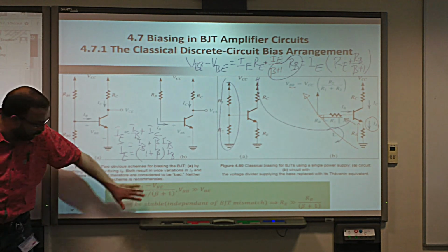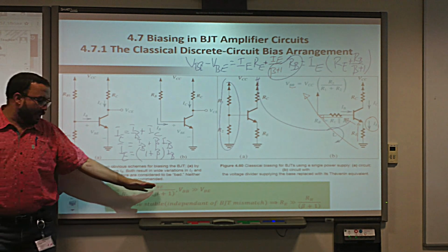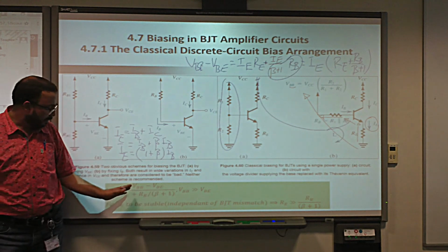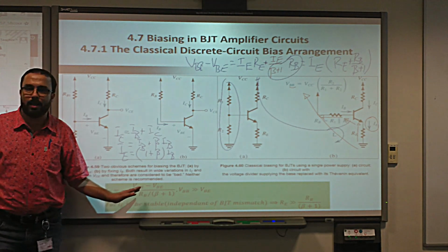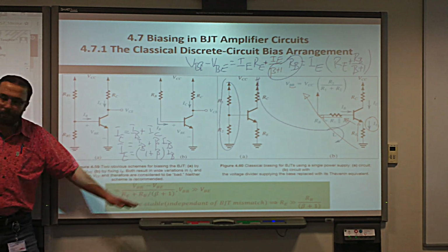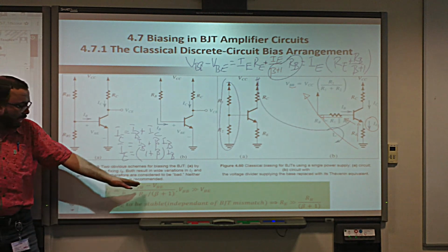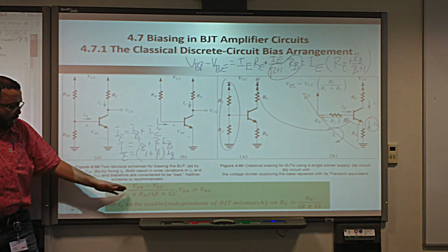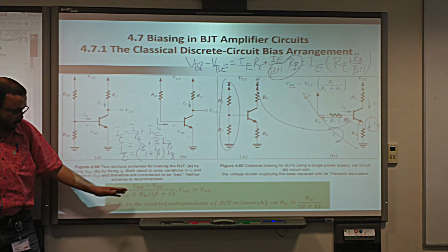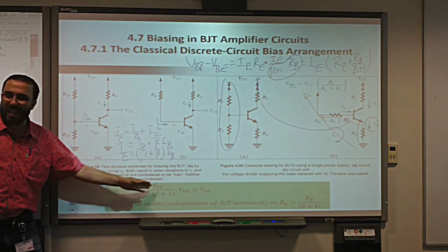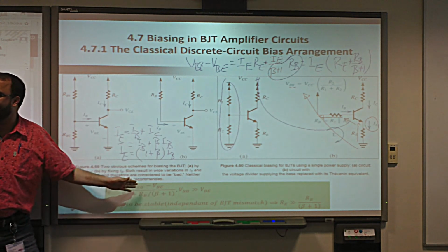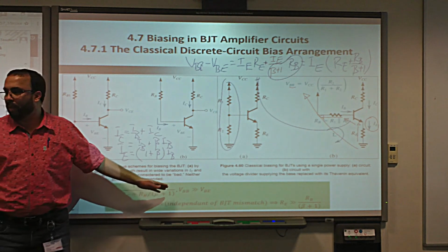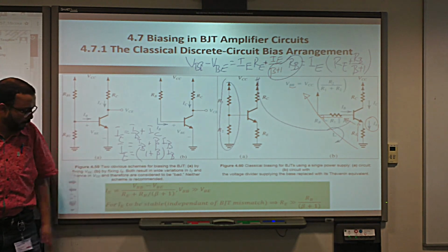Excellent. So now we come to this equation. Usually VBE is actually smaller than VBB. Usually this one is in the 5 volt, this one is in 0.7, 0.5. So we can neglect VBE compared to VBB. Not neglecting, but it will not have too much of a change on it, okay? Plus or minus 0.1 volt, who cares about this? It doesn't make a big difference.